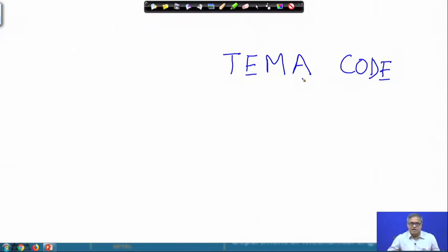And there are design codes, etc. Suppose somebody is a practitioner in heat exchangers, a design engineer, a heat exchanger engineer, he should be very thorough with the TEMA code, TEMA standard. Particularly the mechanical design, which we will not cover in this course, some manufacturing aspects, mechanical arrangement, seals, gaskets, supports. If somebody wants to find an entire solution of the heat exchanger design, one cannot but consult the TEMA code.